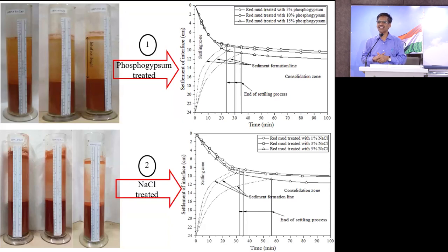Okay, pH. If you see, suppose I am a civil engineer. When will the steel start corrosion? Contact with air and water. That means pH reduces. Unless pH comes to 10, the steel will not corrode. That's why I am putting cement concrete. pH is 12.5, 13. That's why steel will not corrode if the pH value does not come down to 10.5. So after the structure is old, when I am checking it outside, I check it in terms of electric voltage. So when we are talking about pH as hazardous, that is hazardous to what metal?